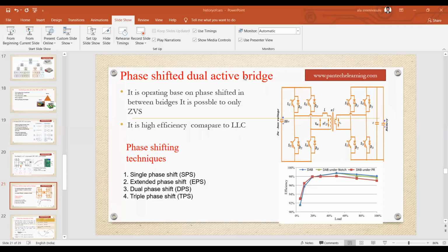Isolated and non-isolated DC-DC converter topologies, we are using both, depending upon the product. Now I will talk about the electromagnetic interference or noise problems. When we are using SCR or BJT, we can utilize switching frequency only up to 100 kilohertz. Nowadays with MOSFET or IGBT switches, if you are using a MOSFET switch, we can go to more than 250 kilohertz switching frequency, so we can operate the converter topology up to 250 kilohertz.